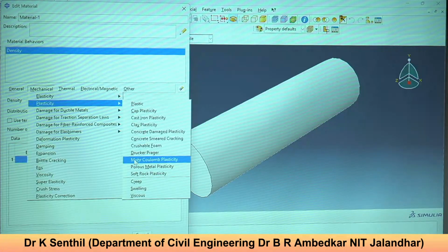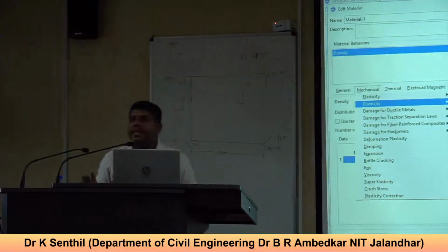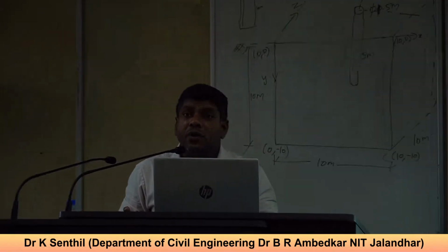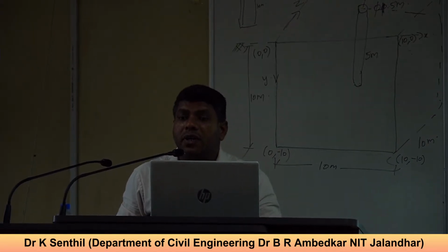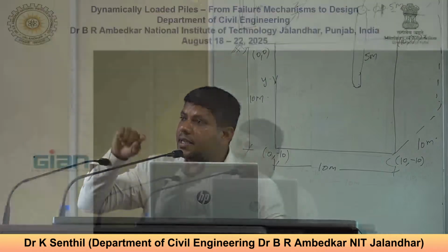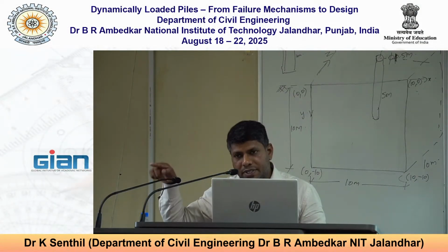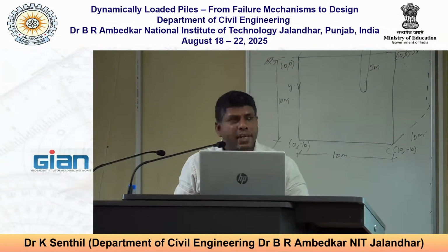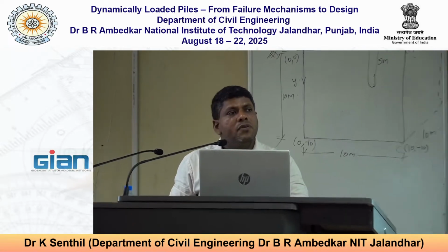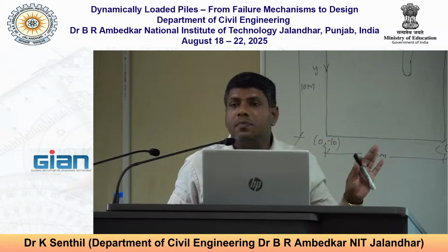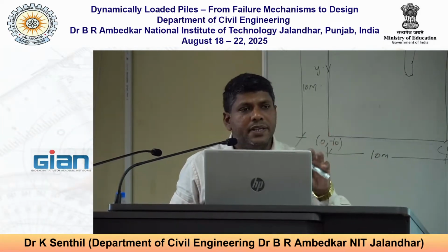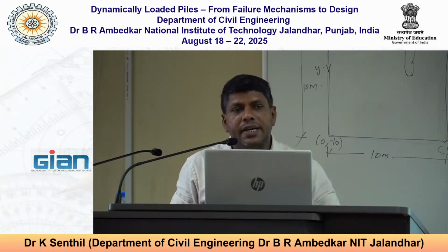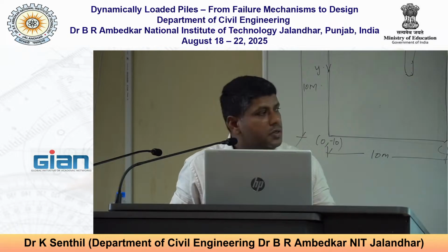Otherwise, for example, I'll tell you, we work extensively on concrete in India, with the concrete damaged plasticity model. In the last 15 years I couldn't find anyone characterizing the concrete. They just put in a grade of concrete and get a compressive stress versus strain behavior and a tensile stress versus strain behavior. That's it, and nobody did more. Similarly with soil, I couldn't find anyone who actually characterized even the Mohr-Coulomb model parameters, because they just pick from the literature. We need a very simple test, but of course some of the tests need advanced equipment. So you can select any one.